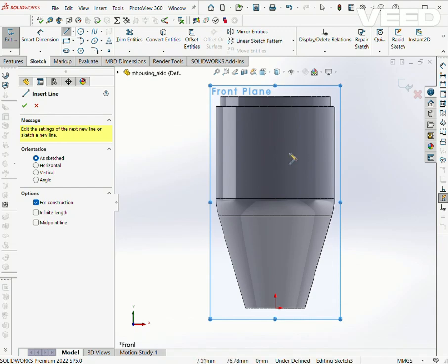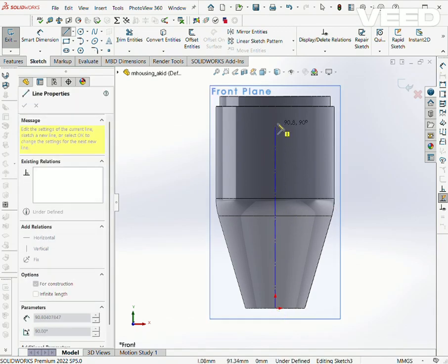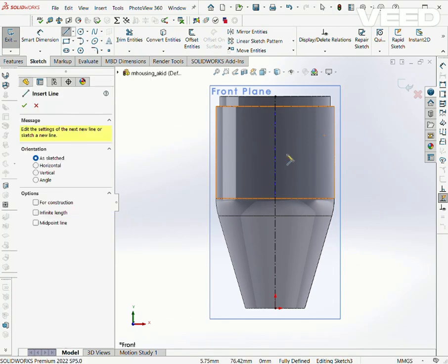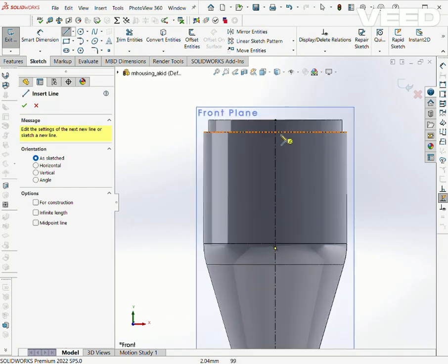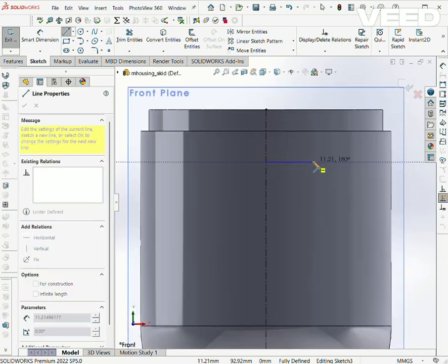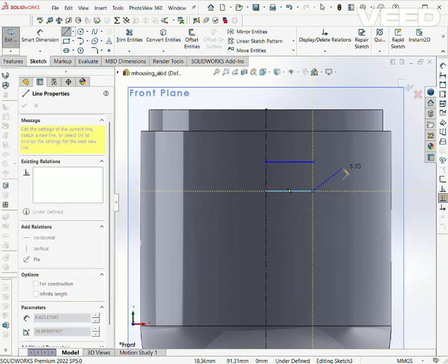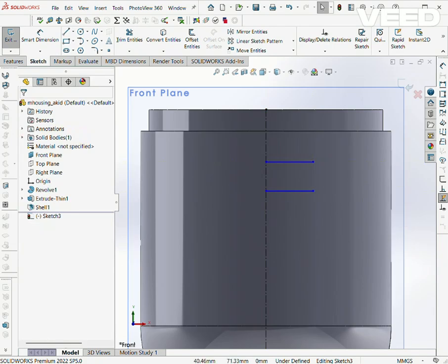Okay, click Center Line here, and sketch a vertical center line to the origin. So this one here, vertical line right to here. Okay, nice. Let's click on this icon here, Line, and sketch 2 horizontal lines of equal length beginning at the center line. So approximately about here. Let's zoom in. 1, and then another 1, 2.